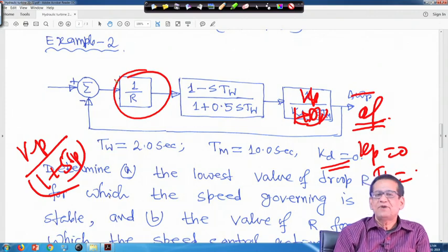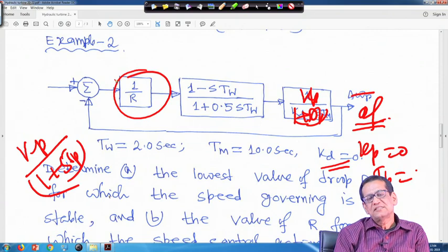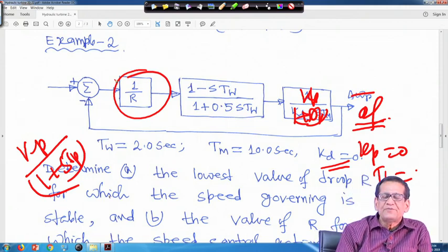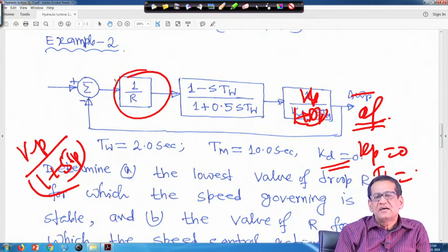It varies from unit to unit, steam turbine to steam turbine, but generally it is 3% to 10% per minute. For a steam turbine the generation rate increasing or decreasing is more or less the same, whereas in the case of a hydro turbine it is not like that, right.